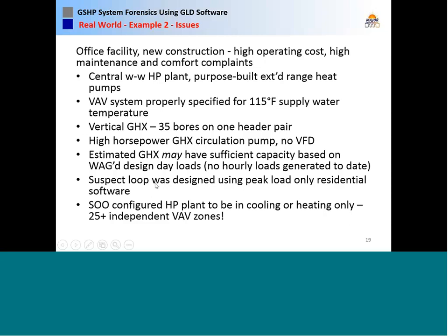Because no one could provide hourly loads, we just did an estimate until we get those loads, using design day loads, and I'll show this in a moment, that maybe the loop is sufficient, but we can't tell for certain. We do suspect from some of the paper trail that the loop was designed using a peak load only, using residential loop design software, so it's not accounting for the internal gains of a commercial building.